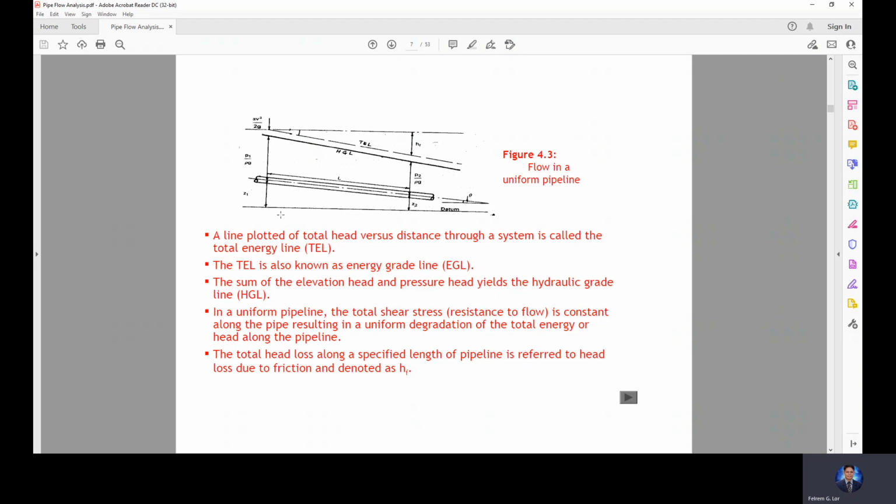Then it is practical to assume that our datum, our reference, is horizontal, meaning it has the same elevation for practical reasons. So we will refer our energy computation from our datum, a certain horizontal line. So we will start at 0 here.